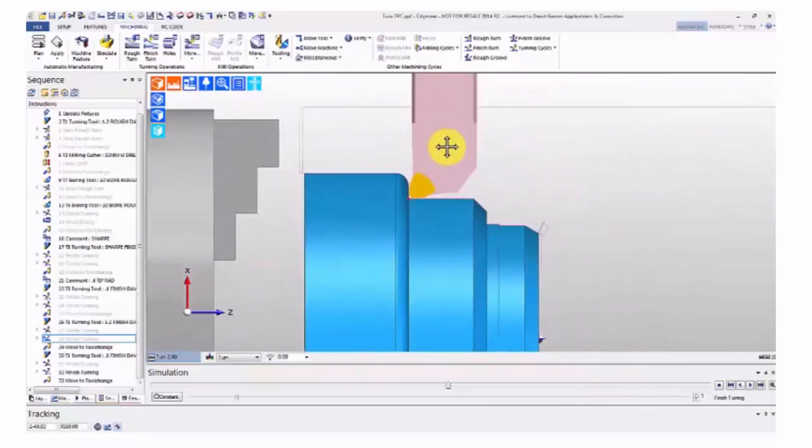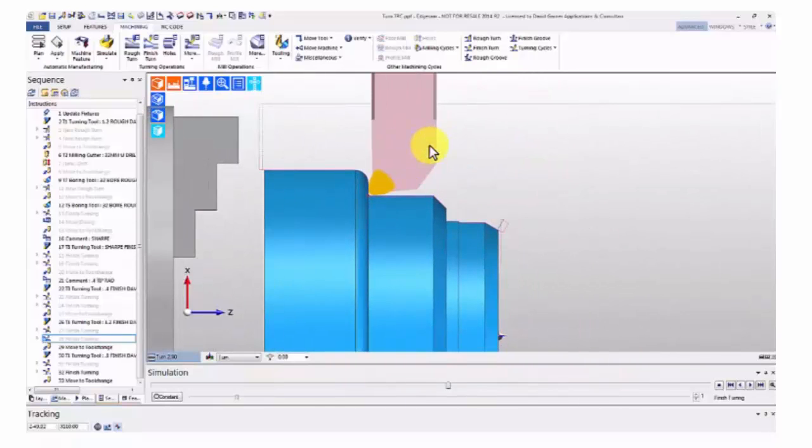What I recommend people to do to troubleshoot these programs is, first thing I would do is take out the G41 or the G42. And then secondly, having taken them out, I would start to break the code down. So I would delete the code sort of working backwards. So first of all, I'll just do that bit, then just that bit, then just that bit, until I get to the point where it doesn't work, and then I'll know exactly what I'm working with.